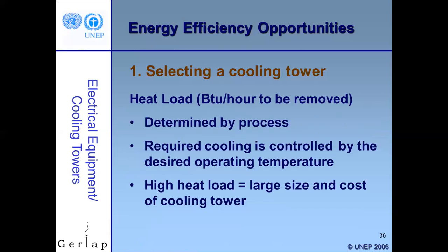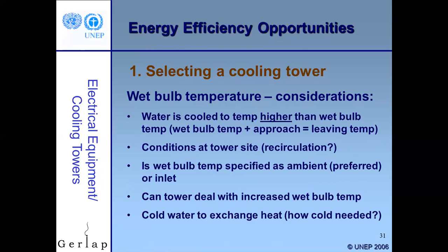Okay, heat load. This looks like it's redundant. Anyway, wet bulb temperature considerations. Water is cooled to a temperature higher than the wet bulb, we know that. So the leaving water temperature is the wet bulb plus the approach.